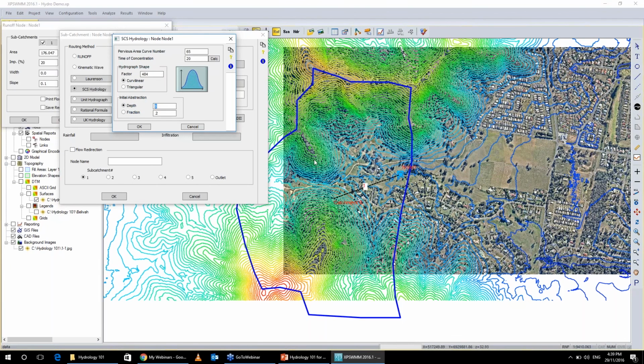And for this catchment, a real-world value might be as high as 15 millimetres or 10 millimetres as an initial loss. But I would have to be modelling a storm from last week, the flood from last year, some historic rainfall data before I would prefer anyone use an initial abstraction value.